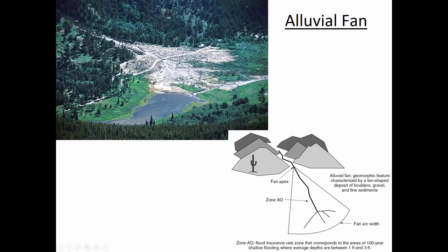Now, an alluvial fan, like I talked about before, is the mouth of a canyon, and this kind of illustration shows that typically what you'll have is a cone-shaped distribution of sediment that's being settled out. And the reason for that is that what settles first, when the water comes out of a canyon like this, the depth is decreasing as the flow spreads out, and that makes it so that the velocity is decreasing as well. So it's usually larger rocks and stones that will settle out first, because they're the ones that need the fastest scour velocity to become mobilized.